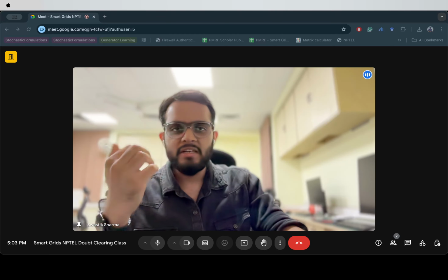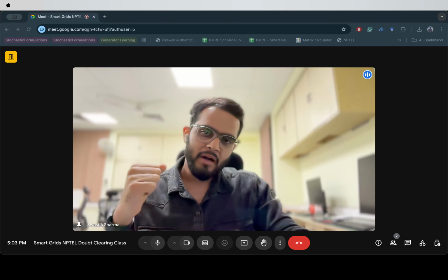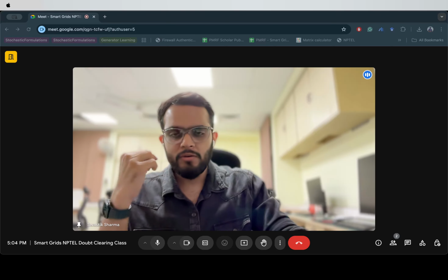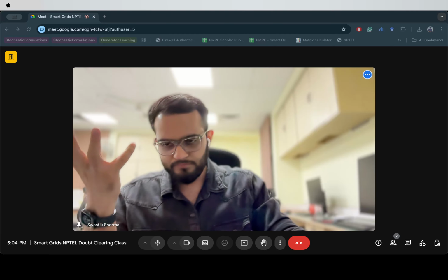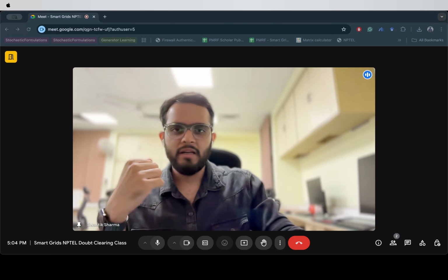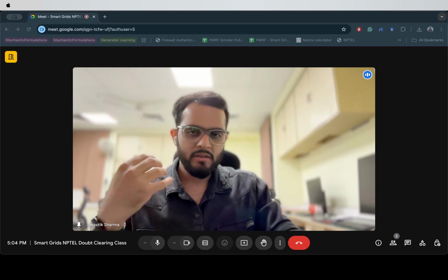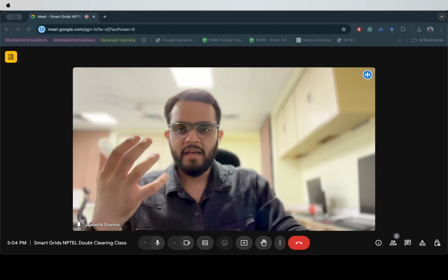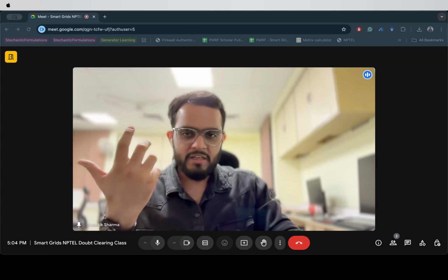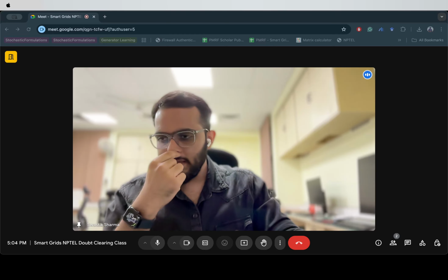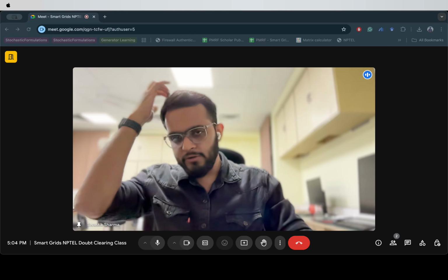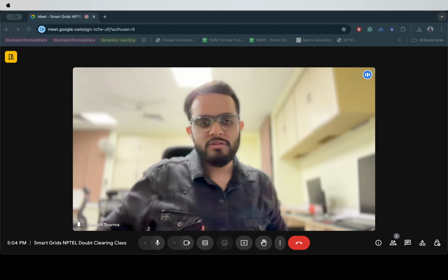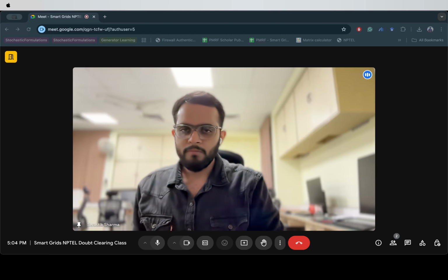Then if that validation is successful, we move towards power hardware in loop validation, where we keep all the power hardware also in the loop. For example, if we are proposing controller logic for a converter, or protection logic for a relay, we do the validation on the real system. And if that is also successful, then we are ready to deploy it in any field or test pilot. That is what these demonstrations over the next few weeks will focus on.